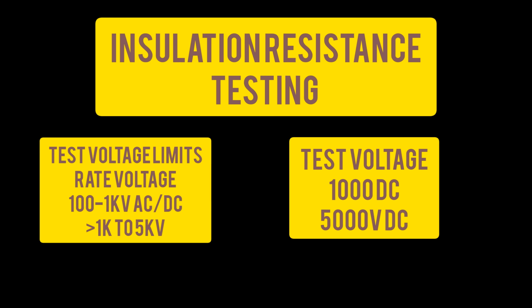For the insulation resistance testing, the voltage shall be applied, number 1, between primary to secondary plus ground, covered during the switchgear test. Number 2, secondary to primary plus ground. And number 3, secondary core to core. For the test voltage limit, the ambient temperature should be considered and shall be noted during your testing. Okay?